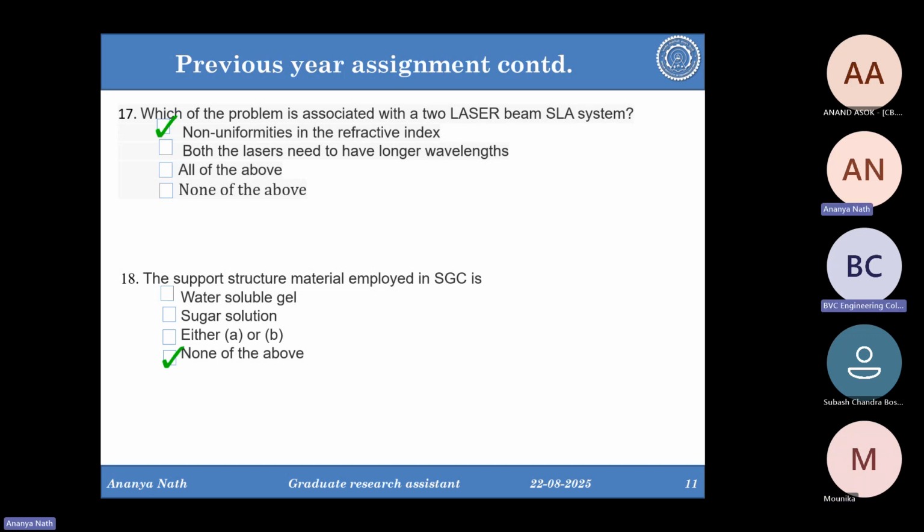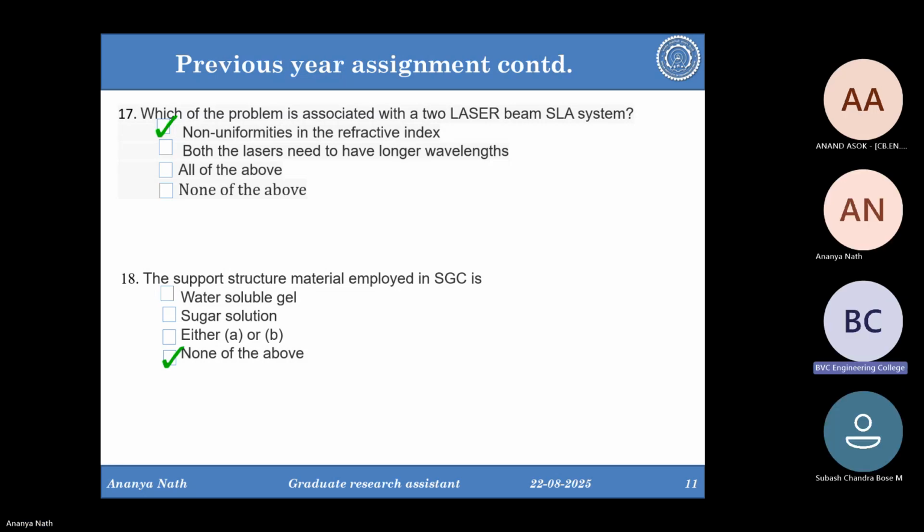In top, you start as if there is only one layer of resin present in between the vat surface and the build plate. Yeah, a lot of resin we are using in the vat. But the laser or the UV light is coming on top of the build plate only, not in the whole resin. The build plate is where you are starting the building process from.